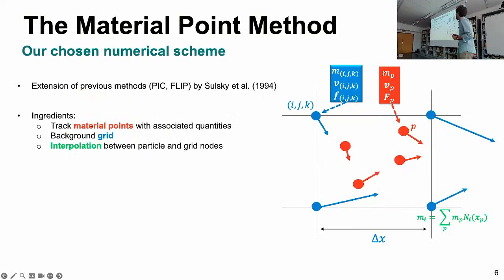So what is the material point method, or MPM for short? This is the numerical scheme that we are using because it's really great at modeling extreme deformations of solids, also as it transitions into fluid behavior. And so historically, this is typically attributed to Deborah Sulsky and her coworkers from New Mexico in their 1994 paper, but you can also see it as an extension of previous methods, in particular particle in cell methods and the so-called fluid implicit particle method from the 80s.